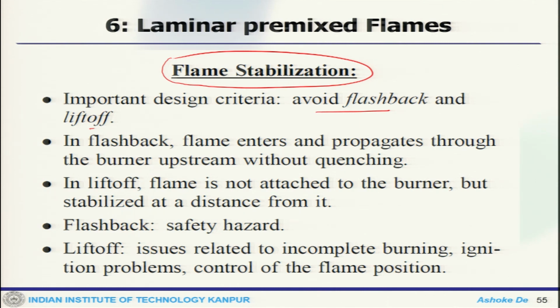The reason is very simple, because your fuel and air are already mixed before they get into the combustion chamber or the reacting system. So, this is the major source of concern, because once you have a premix mixture which is always exposed to the reaction, any transfer from the other side, heat source or radicals or anything, can ignite this mixture instantly.